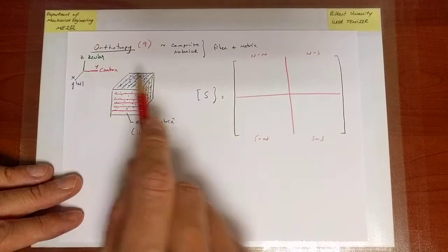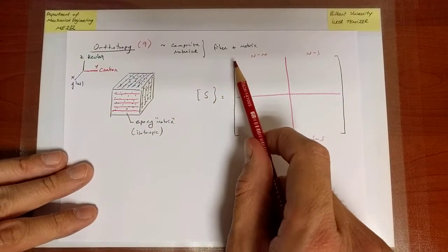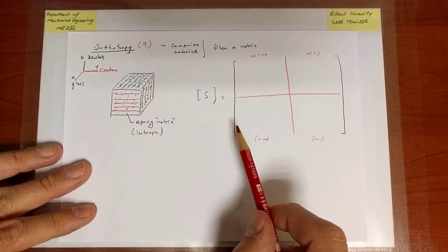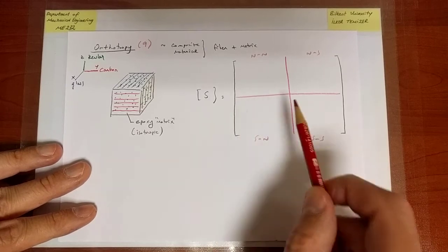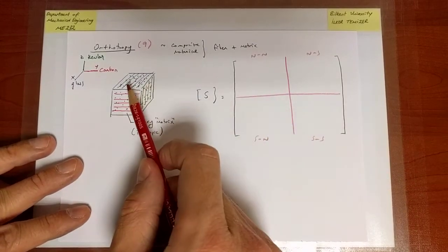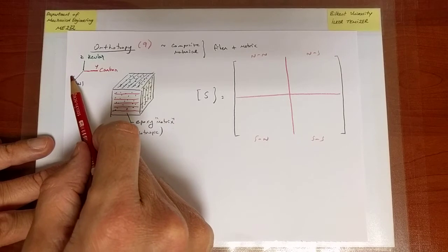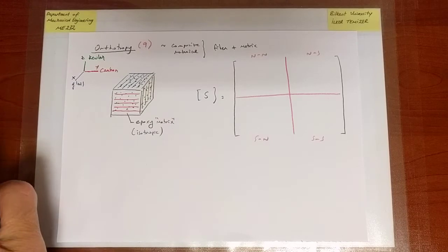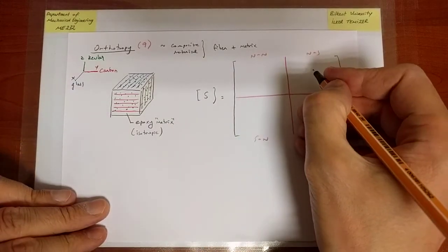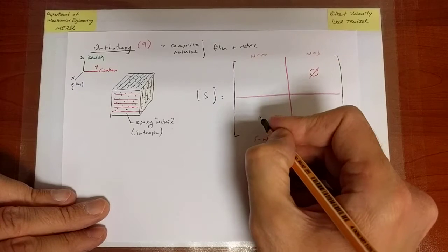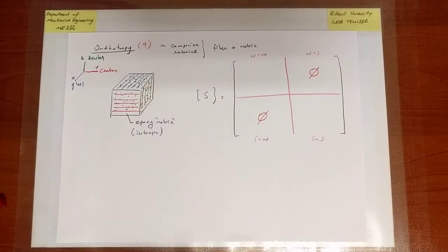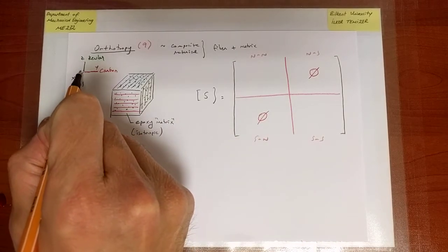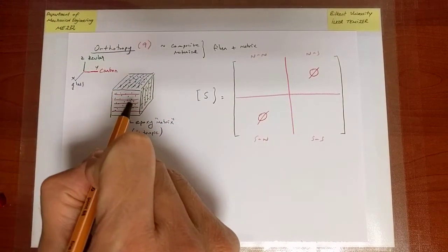So here as well, those components of stress and strain will be related to each other by the compliance matrix. And the choice of the coordinate system will influence the way that matrix looks. Presently, for an orthotropic material, I've chosen a coordinate system that aligns with the fibers. Because they align with the fibers, the off-diagonal components, block matrix-wise, are identically zero. So there doesn't appear to be normal shear coupling. Why? Because I've chosen my axes to align exactly with the fiber directions.